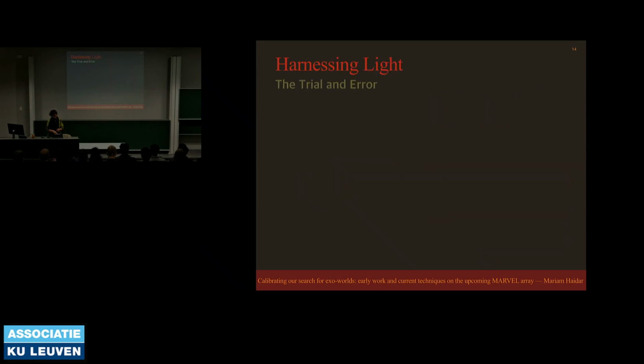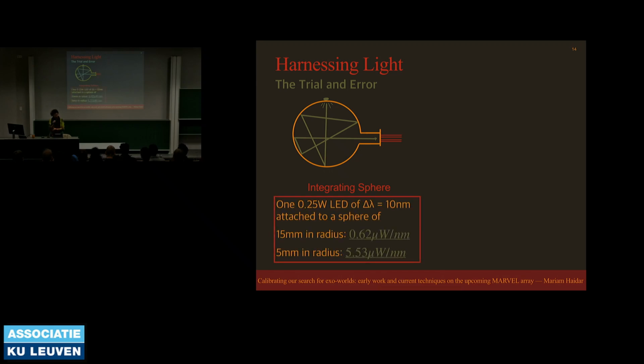That can all fit into one fiber. And so we went through different designs for how to achieve this, how to get multiple LED light into one fiber. The first being the integrating sphere. The idea of this tool is that you would have a sphere that has a highly reflective surface on the inside, and we would drill multiple holes, or we would call them ports, where we would inject light from different LEDs, and the LED light would undergo multiple reflections before it comes out here in the fiber. And so I did a lot of theoretical work with that and found out it didn't materialize into something we wanted to follow, so it ended there.